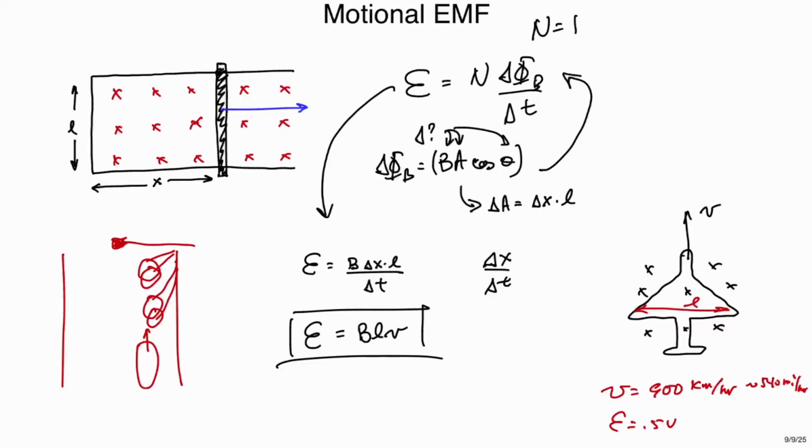As your car moves over that big coil, the coil can sense the presence of the metal of the car. The coil actually has a very weak current that's flipping around in it. And as soon as any metal gets close to it, it affects the magnetic field in that coil. And Faraday's law of electromagnetic induction starts to cause changes, and Lenz's law says, no, I don't want to change.